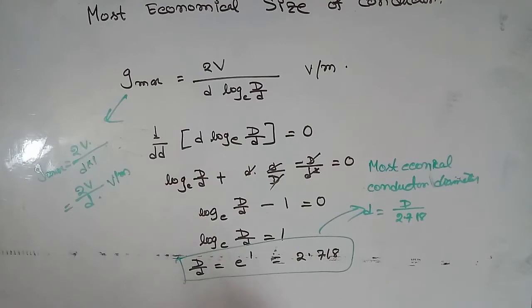Now there are three ways of doing this without excessive copper. First one is using aluminium instead of copper, because for the same current, diameter of aluminium will be more than that of copper. Next, using copper wire stranded round a central core of hemp. Third one is using a central lead tube instead of hemp.